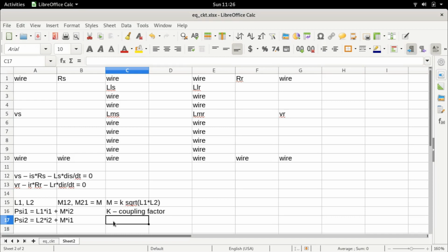So usually, if you have a fairly well coupled system, this can be anything in the range of 0.95 to 0.99. You usually don't take it as 1 because there is always some amount of leakage, right? You can even take it as 0.95 or something, whatever. Now in the case of an induction motor, because there is an air gap, you can assume something of 0.98 or so, right? So you can say around 2% of the flux produced goes into leakage, does not associate with the stator or the rotor, but rather is leaked into the air.